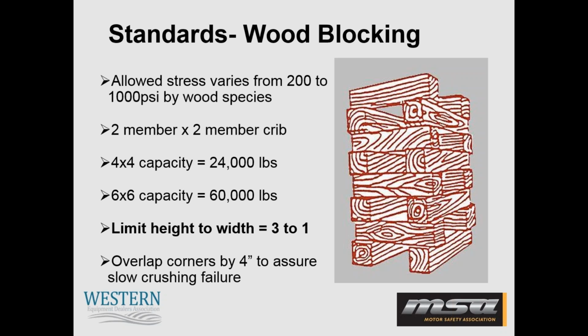And when you are utilizing it, be sure that it is done correctly with hardwood as seen on the chart on the left, as well as the picture on the right. And you also want to never use plastic blocks for cribbing, as they can also be slippery or shatter.